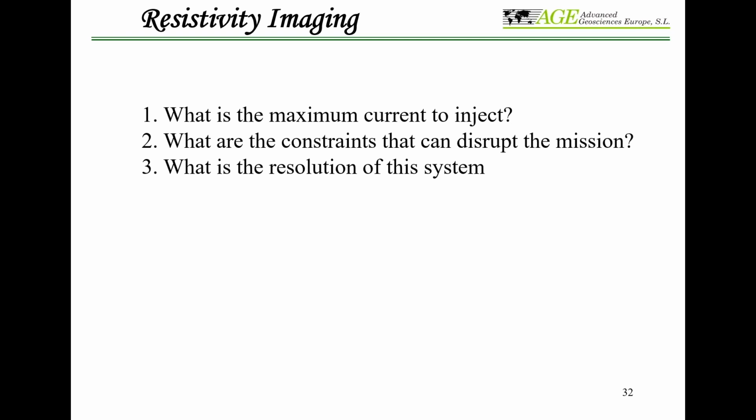If you use an external transmitter, with 5 kilowatt, 10 kilowatt, or 15 kilowatt power, depending on which version you're using, you can maybe go to 27 ampere current injection. But believe me, 2000 milliamp is enough. You have seen the example for deep ocean bottom studies, with 800 meters of water column and 1,600 meters cable length, using 2000 milliamp current injection, able to get about 150 meters depth of investigation, more or less.